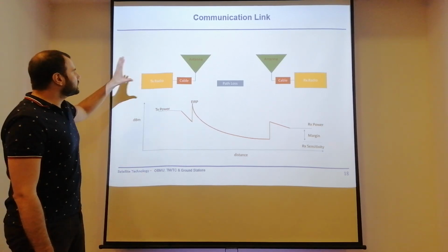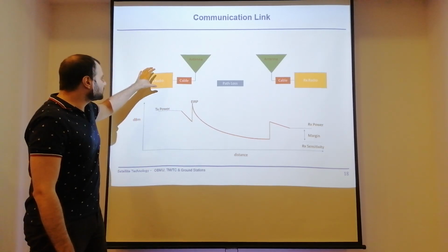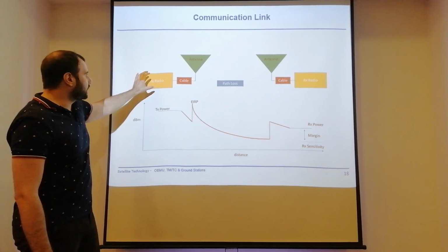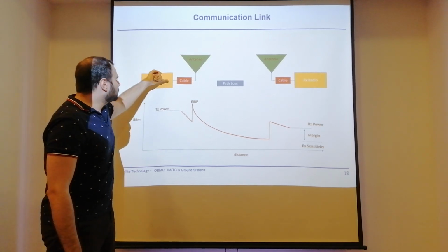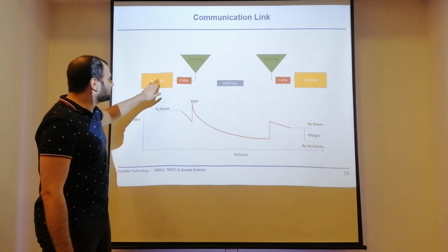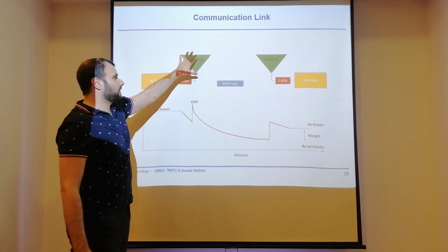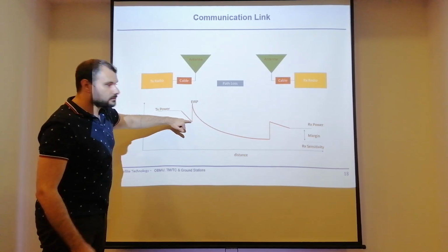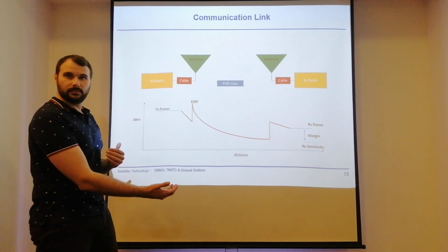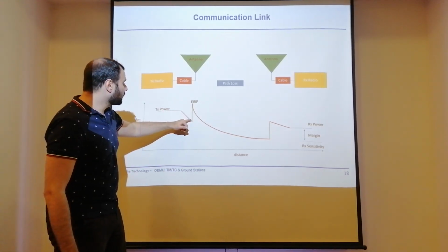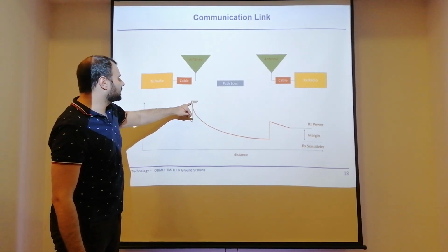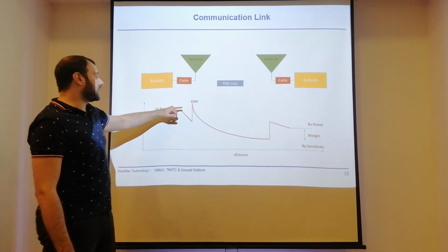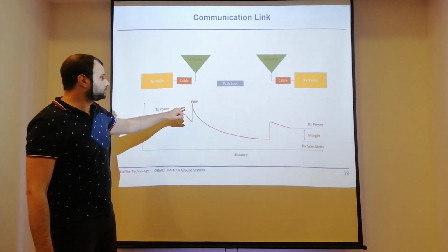Why is it all important to have different types of antennas? So if we have a look at this, we have our transmit radio on board, let's say, our satellite, and this radio, our transmitter, is connected via some cables to the antenna. And we have a certain transmit power, then comes the cable. We lose some of the power, it is attenuated in the cable, and then we have our antenna with the antenna gain, and we get to our EIRP, our equivalent isotropic radiated power.